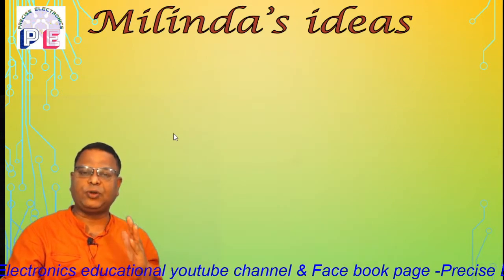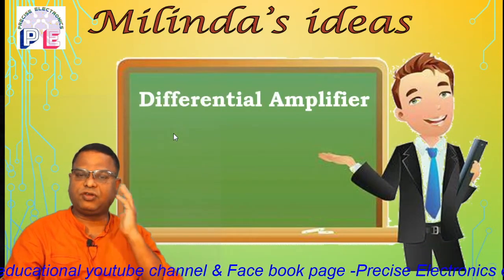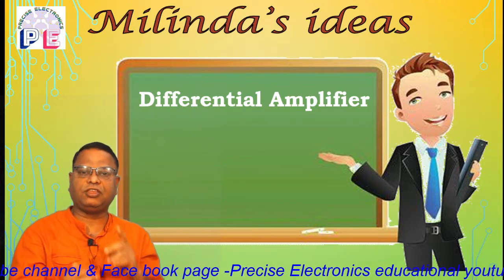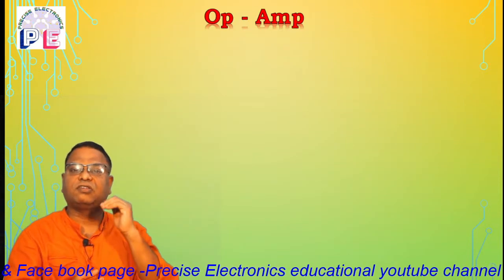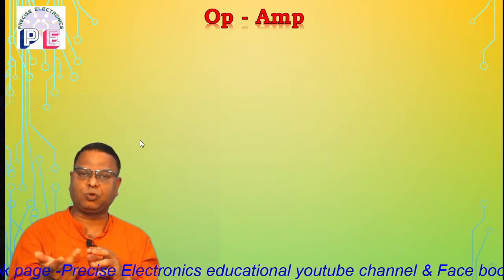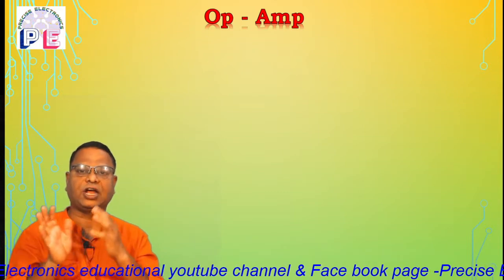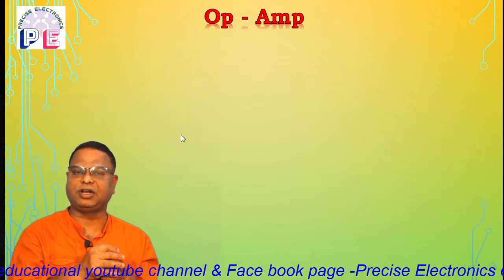Friends, in today's video lecture we are going to study the differential amplifier. What is a differential amplifier? It is the first and second blocks of the operational amplifier. The first block is the first stage differential amplifier, while the second block is the second stage differential amplifier. The first block has two inputs and two outputs, while the second block has two inputs but only one output, and that output is connected to the third block, that is the level shifter and emitter follower.